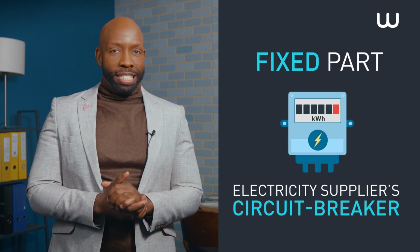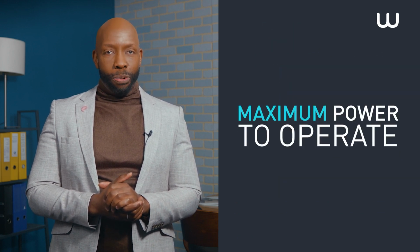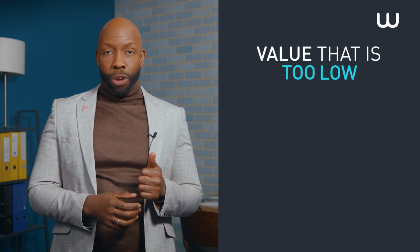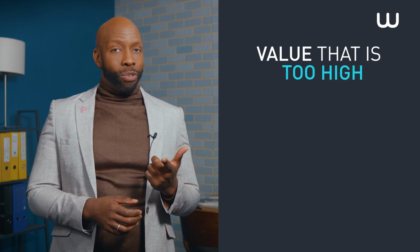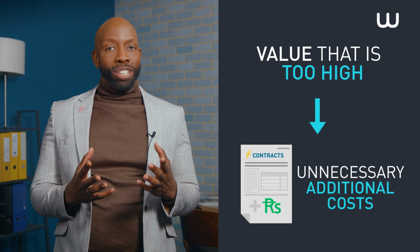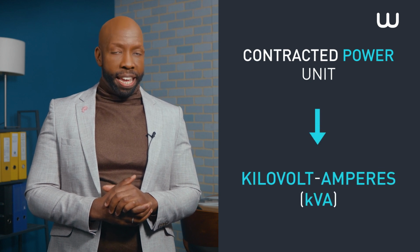It is important to take out a contract with the most suitable maximum power to operate a site. Choosing a value that is too low will generate regular power cuts when power demand is exceeded. Choosing a value that is too high will generate unnecessary additional costs because the fixed charge increases with the contracted power. The power is listed in the contract in kilovolt amperes, kVA.